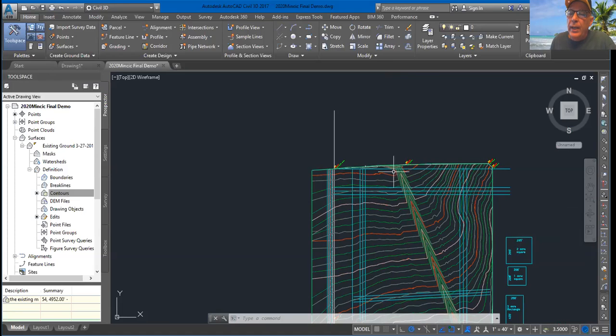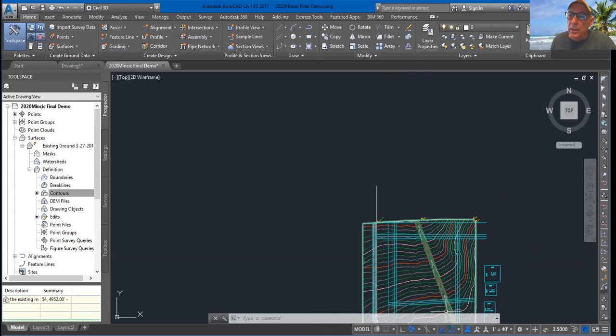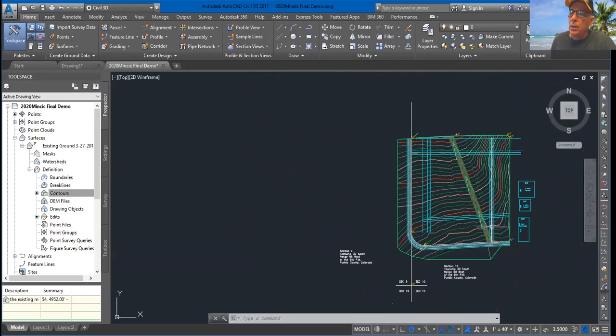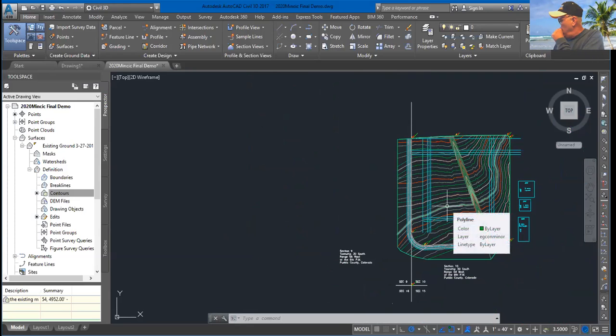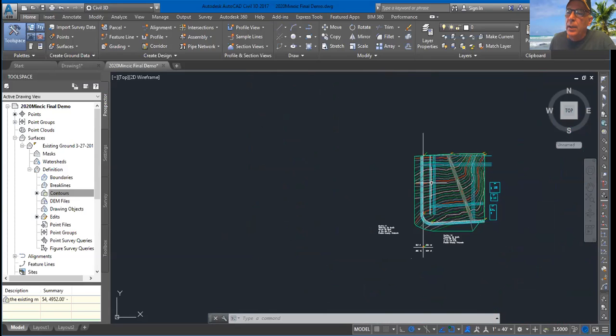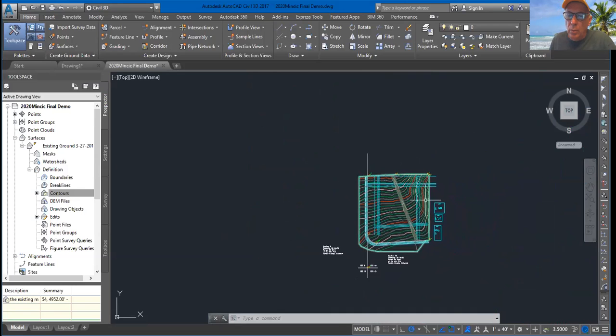Okay, so given that, I have offset this line 208 feet, this line 295 feet, this line 295 feet, and this line down here, I'm looking at, oh, what if I used 2-acre rectangular parcels over here and made some longer and thinner lots along the way right here. So I have decided to set this line 435 feet off so that I would be able to create some larger rectangular 2-acre parcels along this south line here. Excuse me. That's kind of my preliminary criteria, and I'm going to start out by creating a roadway here.